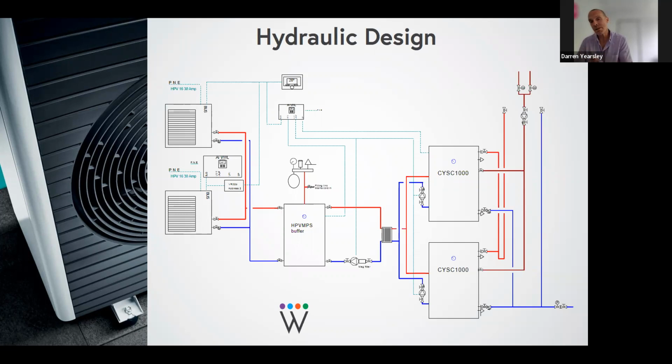The solar system and the heat pump system aren't directly connected together, like physically connected together. They're connected together logically. And the logic is the system can see when the solar system's in production. If the temperature of the water in the tank is less than 70 degrees, the system will then kick into gear and start building energy into the storage cylinders.